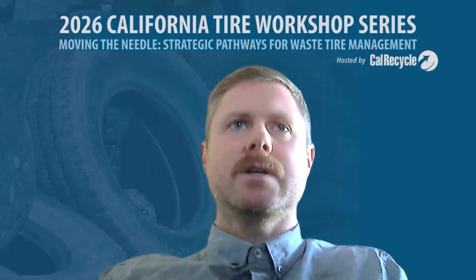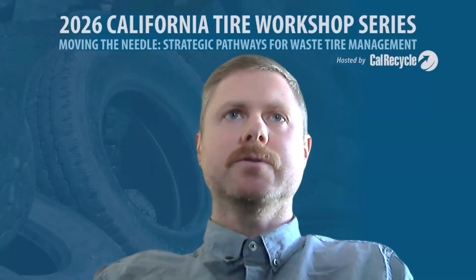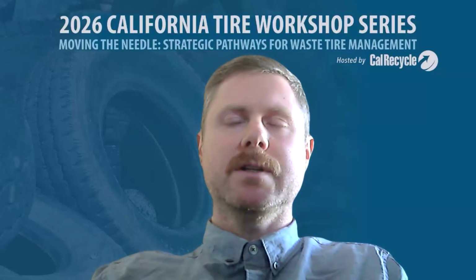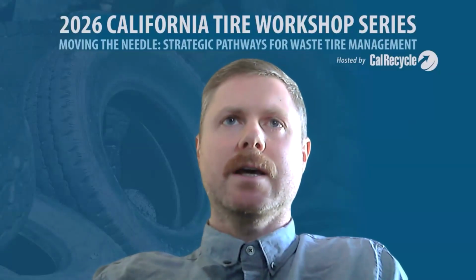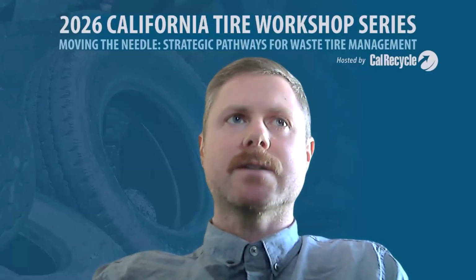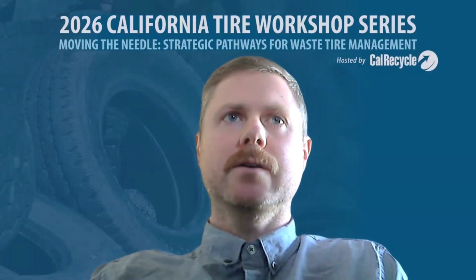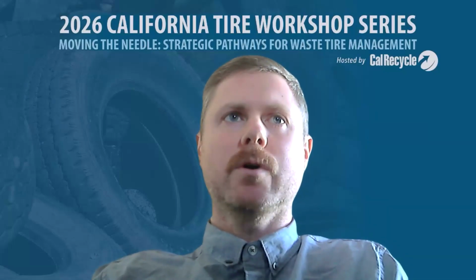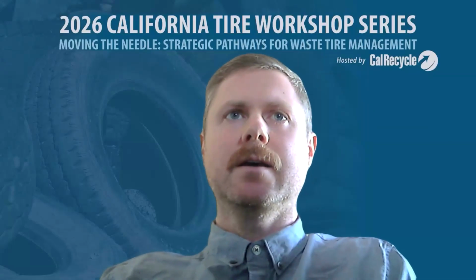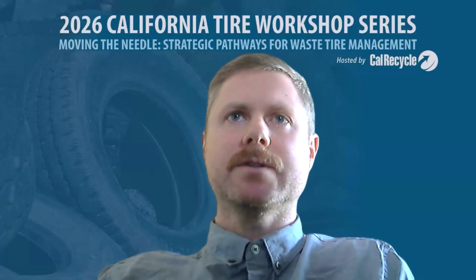Today's session explores how TDA advances sustainable geotechnical engineering and pavement design. First, we'll hear about experimental results on TDA as a low-cost seismic isolation layer beneath shallow foundations and slabs, detailing material behavior and a forward path toward hybrid systems pairing TDA with cementitious lightweight fills.